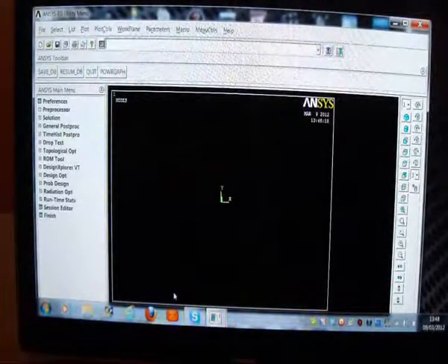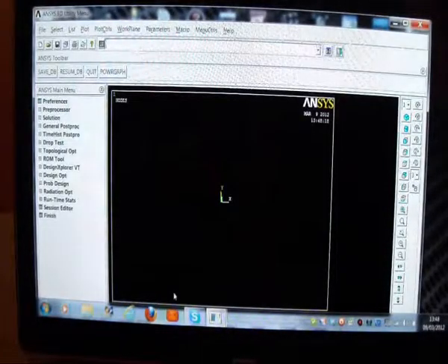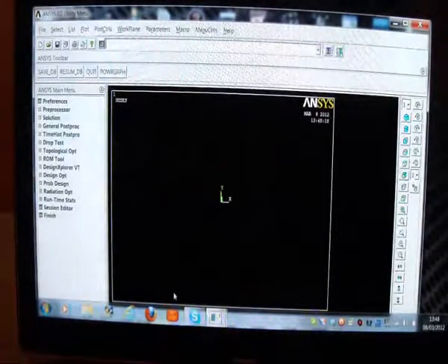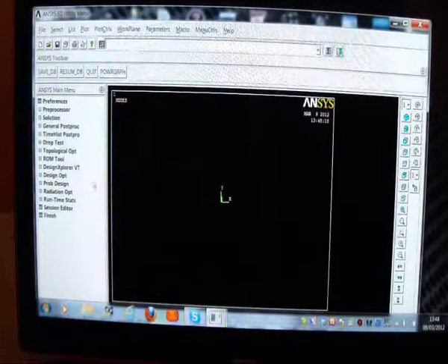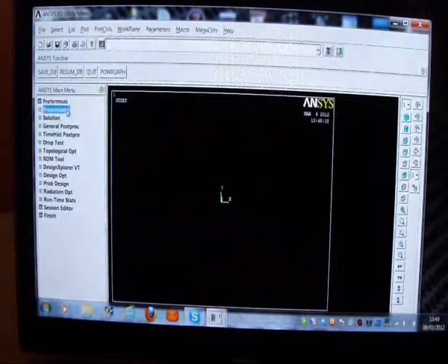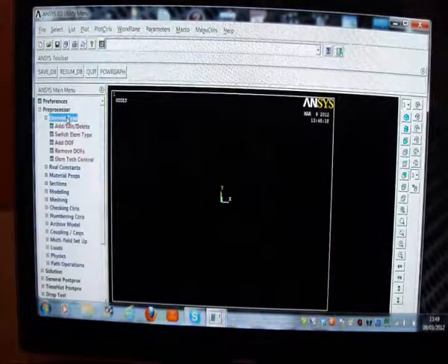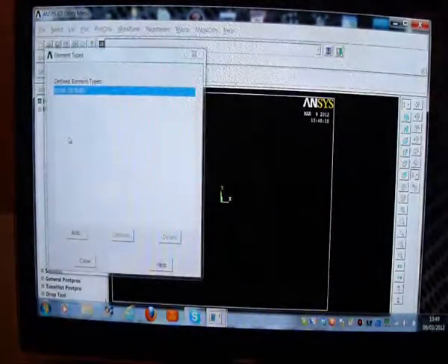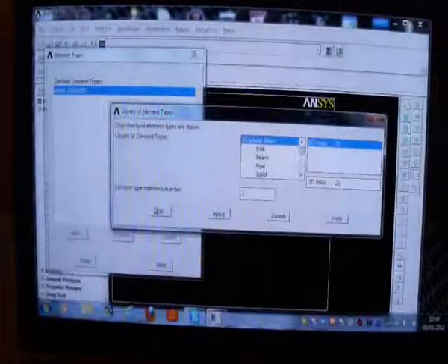I'm going to give a lecture on how to use the commercial computer program ANSYS for analysing the vibration of a ring-stiffened cone. So first I pick on Preferences, I pick on Structural, I press OK, and then I pick on Preprocessor, I pick on Element Type, Add, Edit, Delete, and I add an element.